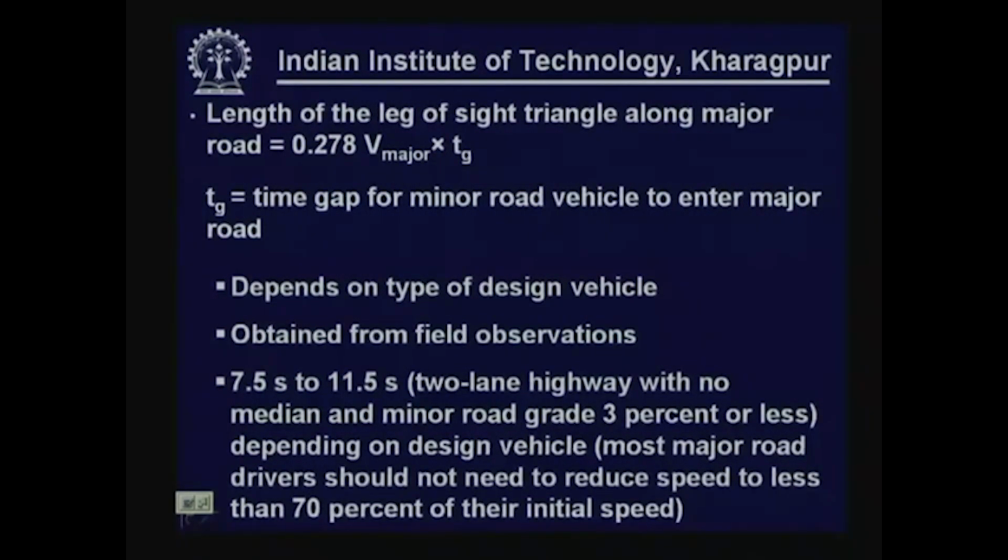And this value of 7.5 seconds to 11.5 seconds as recommended in AASHTO is based on a 2-lane highway with no median and minor road grade 3% or less.